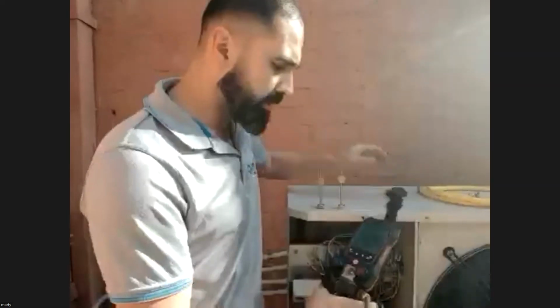I'll explain this. This shows 19K here, even though the evaporator was actually at 8K earlier, as I mentioned. Because the liquid line is touching the suction, you're getting a big delta T, and the system will start to pick up a lot of superheat from there. So you have to be careful of how much superheat is coming back to the compressor, because most compressors have a designed allocated superheat.